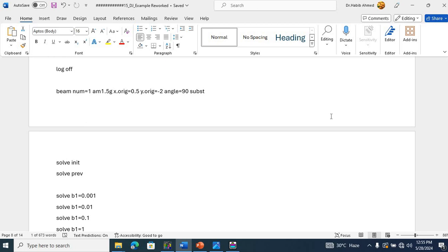So the first step in the solar cell analysis is to illuminate the device. We need to turn on the illumination, and I would do that under AM 1.5 conditions, which correspond to the standard test conditions. So I include beam number 1 under AM 1.5 conditions.